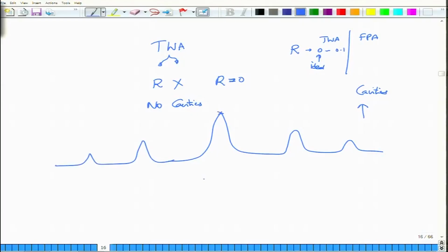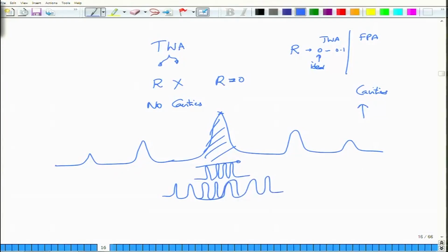So you will have a larger gain here at the appropriate frequencies, and if this is the only frequency of interest that you are working with, then there is no problem. You can easily have multiple channels here within that band, and then almost all of them will have equal amplification, and you are all very good and very nice. Okay, but if your channels actually go around this region, then you are in trouble, because some of the channels will see lesser gain. The travelling wave amplifier overcomes this problem. It gives you almost equal gain, independent of frequency. So this is the travelling wave amplifier, but the gain peak value is actually quite small.